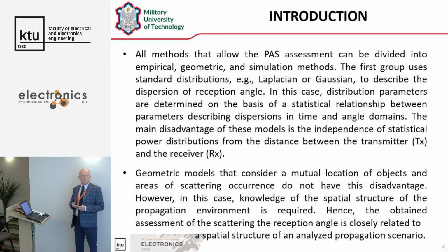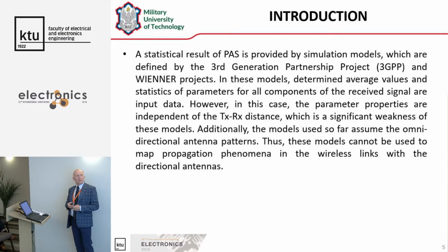Geometric models that consider a mutual location of objects and areas of scattering occurrence don't have this disadvantage. However, in this case, knowledge of the spatial structure of the propagation environment is required. Hence, the obtained assessment of the scattering in the reception angle is closely related to the spatial structure of an analyzed propagation scenario.